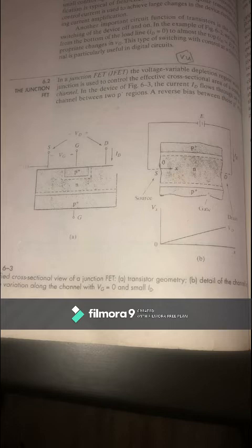Since you have fixed the resistivity of the channel by doping, the channel resistance varies with the change in the cross-sectional area. It means your variable depletion region serves as two doors of a gate which open and close on the conduction channel.